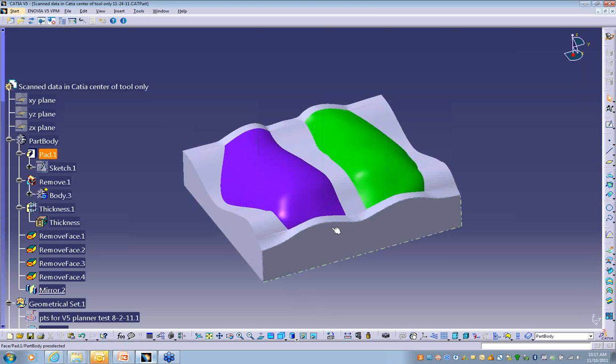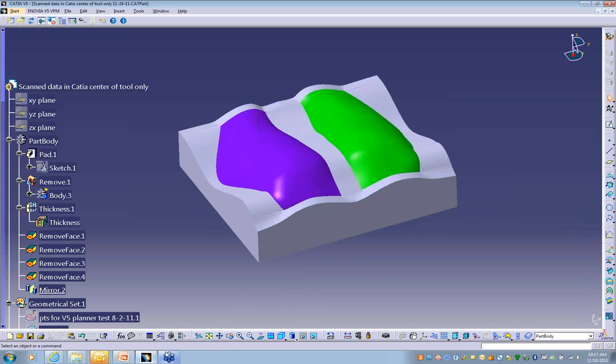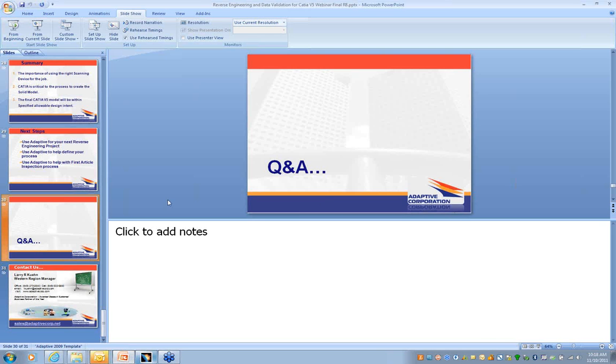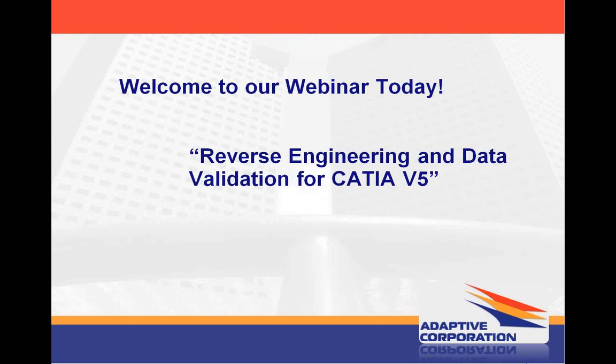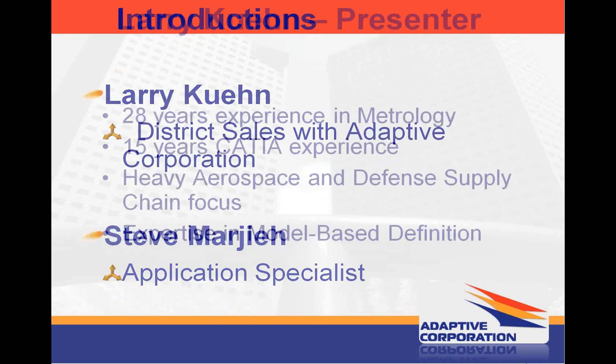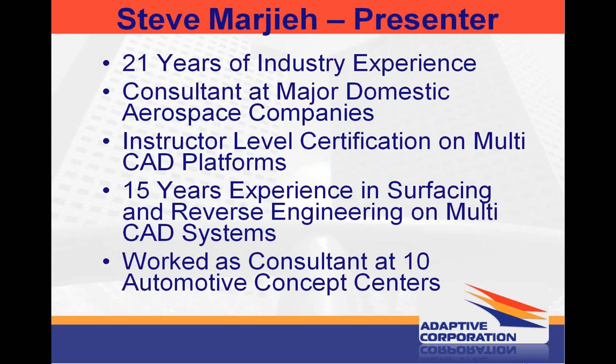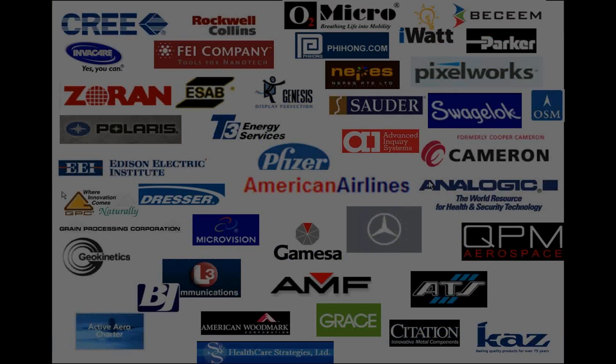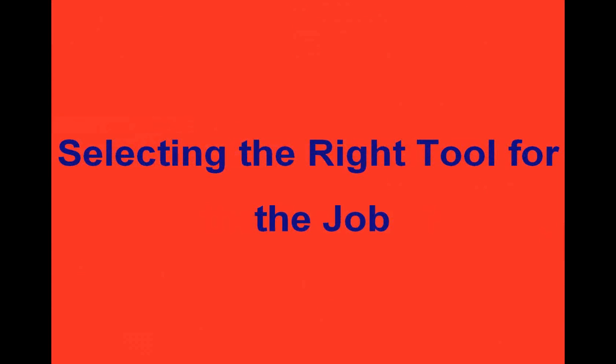All right. Well, there's several solids that are the final resultant of those surfaces. In this case we had part ribbons on the end. Those ribbons were critical to place in there to help with the runoff on the machining of the actual tool. They're not critical to the actual part. So we have to take things in sort of an iterative process. We have to generate the part, we have to generate ribbons or runoffs, or if it's a composite, we have to create the layups and the ramps.